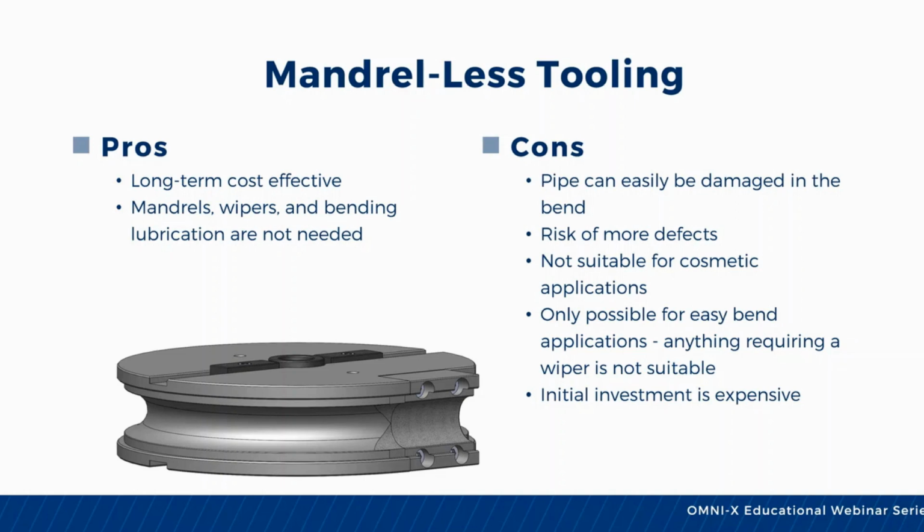Long term, eliminating the cost of mandrels can result in savings. However, the initial tools are much more expensive due to the increased machining and material required to support the impacts. The tube also comes out of the bend with visible defects and isn't suitable for normal aesthetic products.